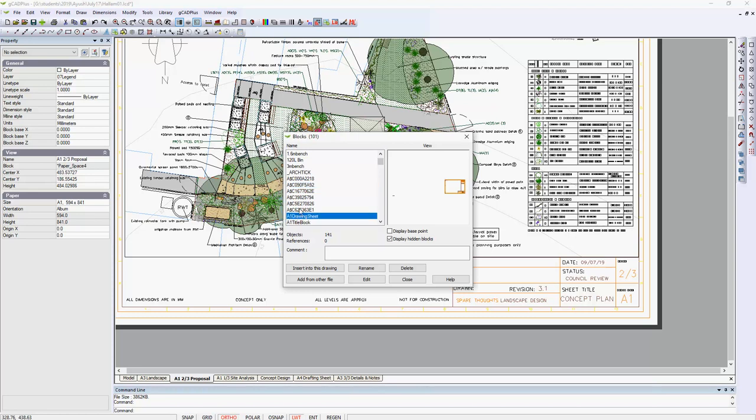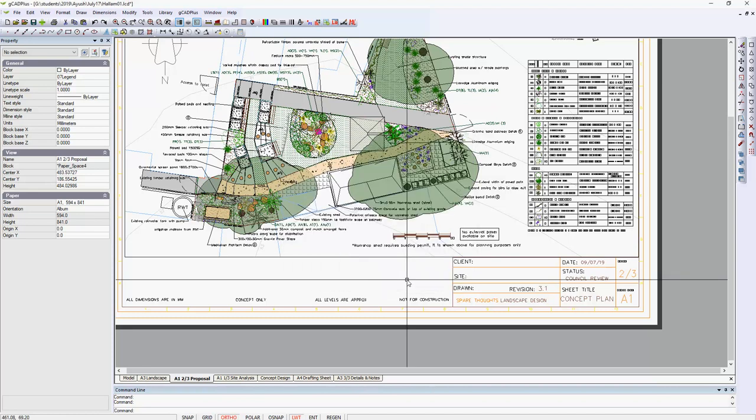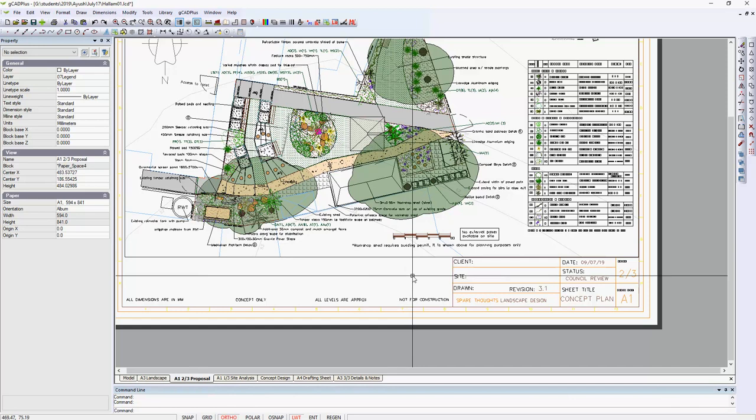Let's just scroll through, and if you find any of the blocks sitting on the shelf in the drawing and the delete highlight comes up, just click it and say I want to delete all unused blocks, and you can see 29 blocks have been deleted, so we can OK that. So now when we save the drawing and reopen the drawing, we hope that the file size is somewhat less.